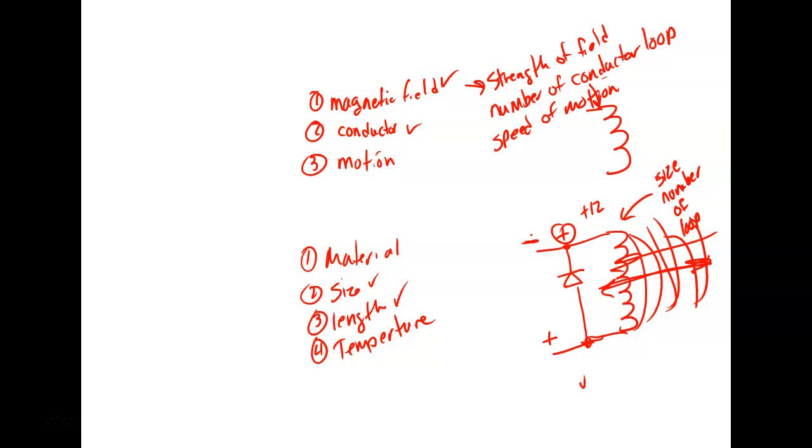So this counter EMF diode in there, some people call it a flyback diode, is there to prevent this. When you turn off that coil, it's in there to prevent that counter EMF from damaging my pressure sensor. So don't take those out, and make sure you put them in there in the right direction, right?